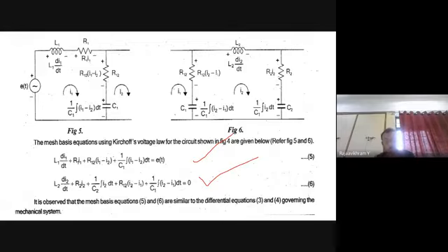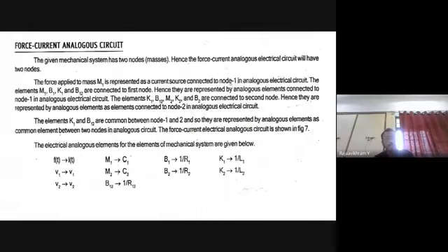Next we have to apply the force current analogy. So in the force current analogy, what is happening? As already informed, for f of t, the input is the current source, I of t. Don't forget that while drawing the circuit diagram, whether the input is a voltage source or a current source. Remember that for the force current analogy, you have to replace the voltage source with a current source by putting the arrow mark. Okay, I of t. So the force is converted into I of t.